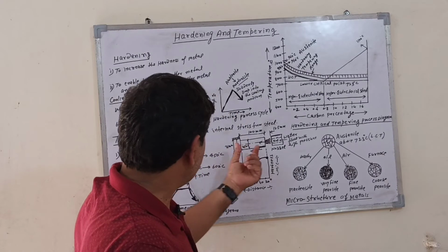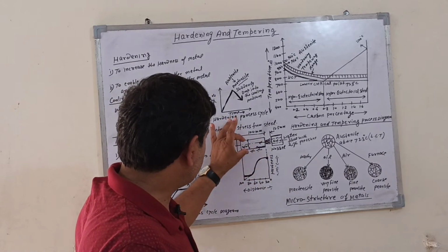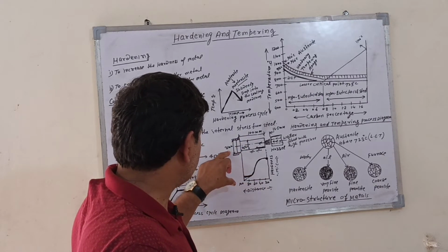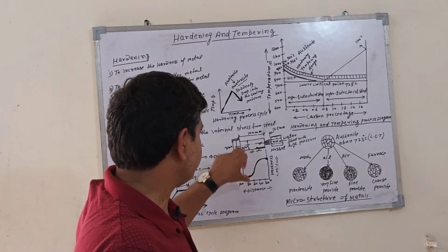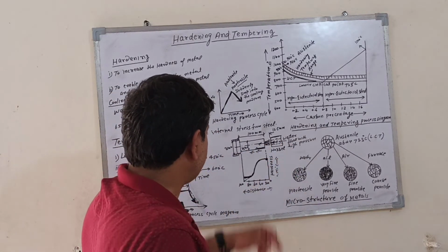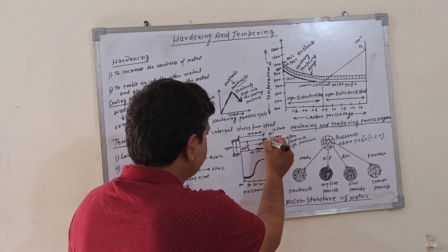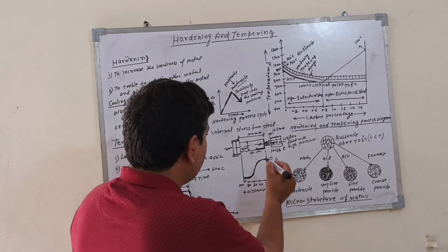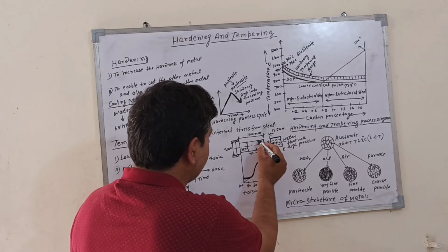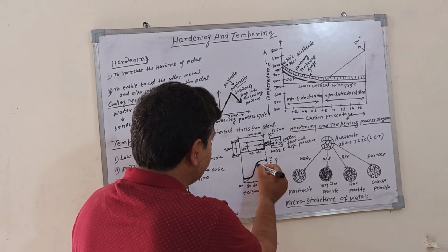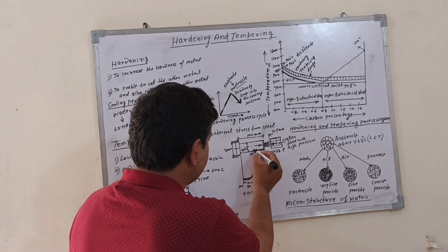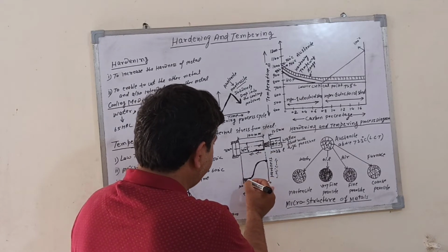This is the specimen with a 100 mm length and 25 mm diameter. The collar diameter should be 31 mm. This is the Jominy test system. Water is applied on the hot surface at high pressure. The hardness gradually increases. After some time, the hardness decreases.